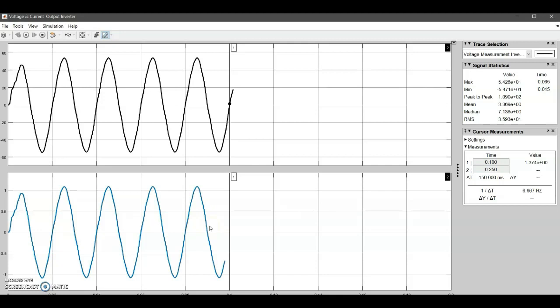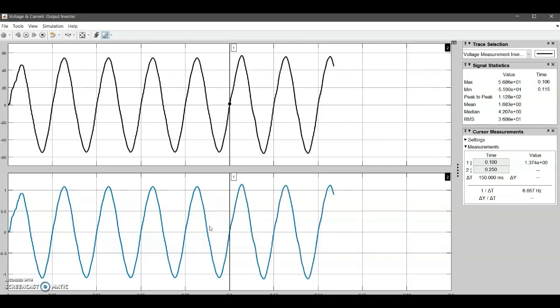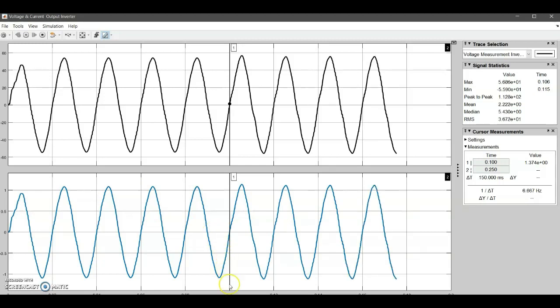It shows that it forms a smooth AC waveform, and at 0.1 seconds here, when my input changes from 24 volts to 21 volts, there is no significant change in the output of the inverter, and it shows that this inverter has an AC waveform output in good condition.